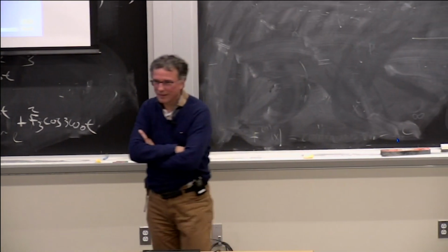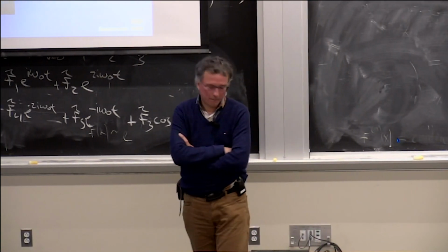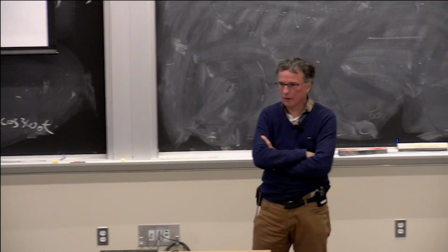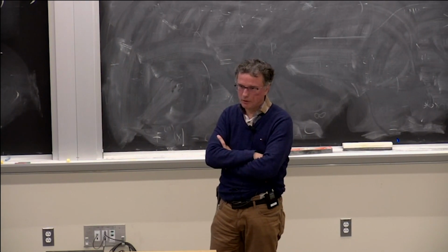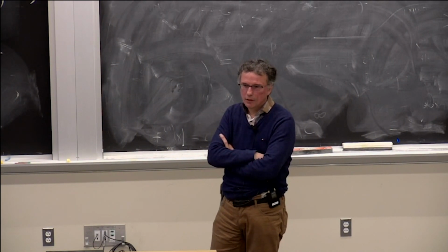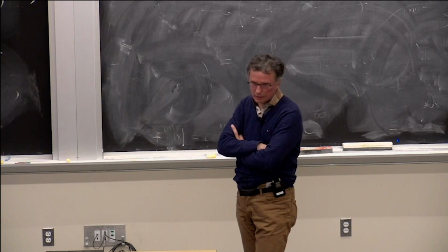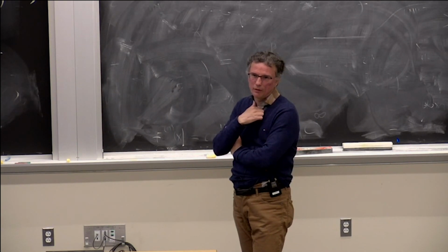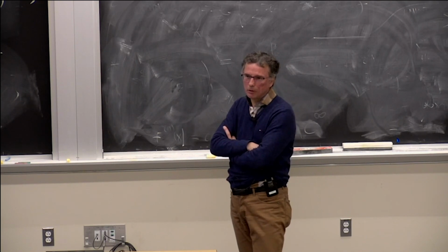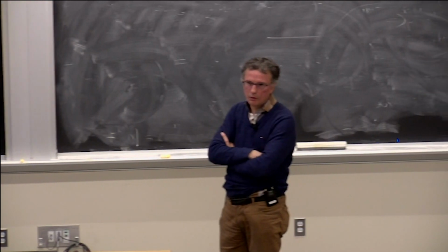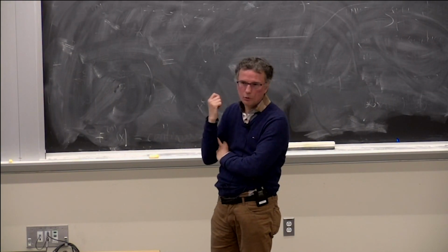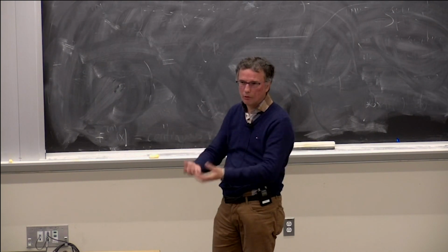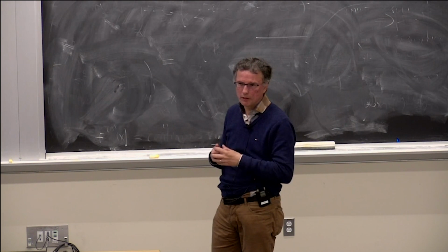So what is the typical frequency of light rail lines? A minimum is 4 light rail vehicles an hour in each direction. That's the minimum. Otherwise, it goes up to 6 or 8 in Delft. And in other cities it can be more. But 8 is pretty much for a city with 100,000 people. And it has to compete with cycling. So many people who cycle, you take them out of the public transport system.